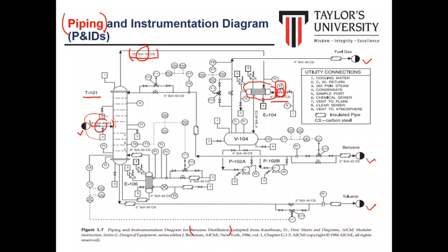And then we also have this temperature indicator, mounted to control the temperature outlet from this shell and tube heat exchanger. You can see here the main stream from the tower enters the tube side. The shell part consists of the cooling medium. So we have a cooling medium on the shell side, and a pressure relief valve here to control the pressure inside this heat exchanger or condenser.